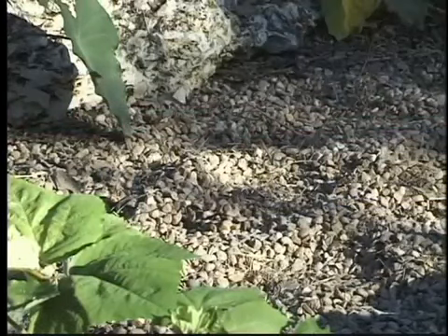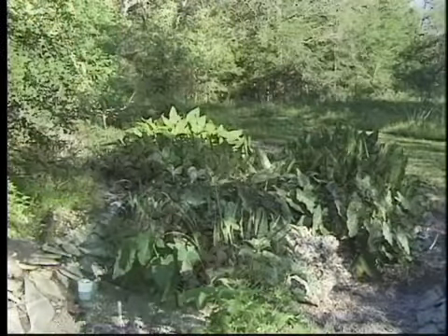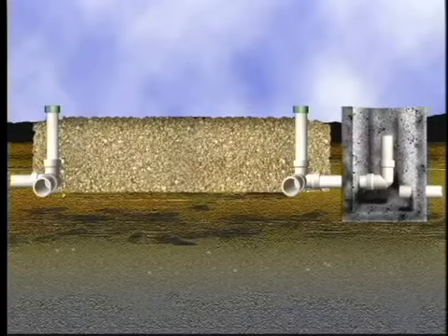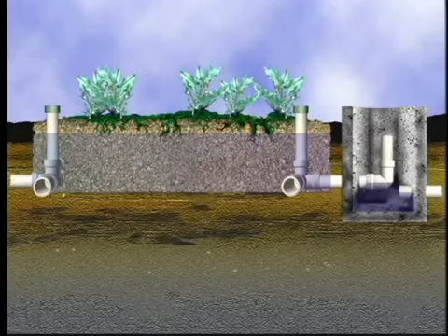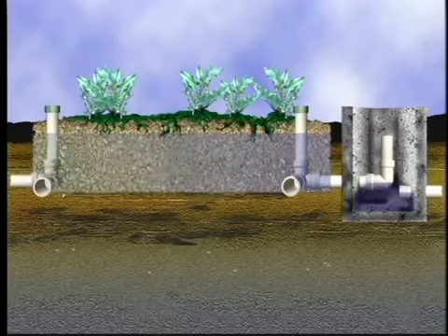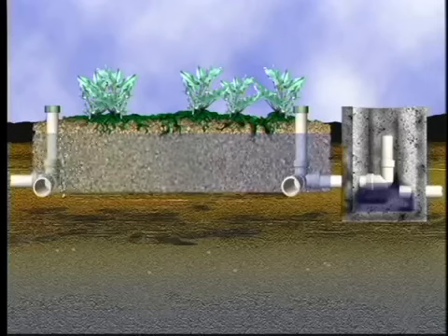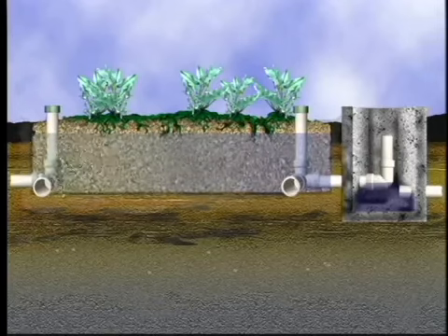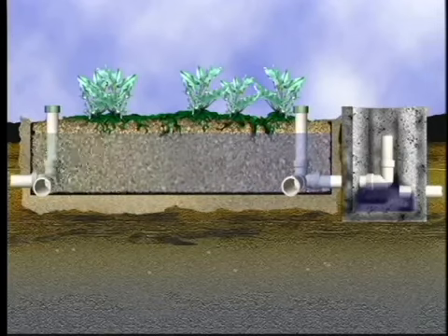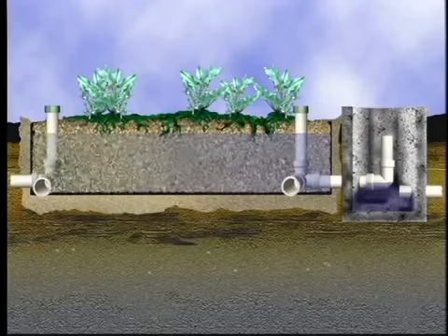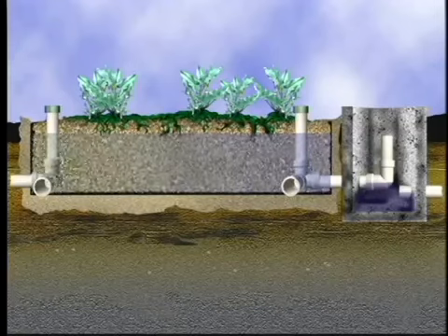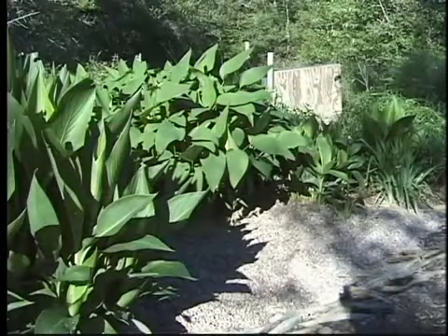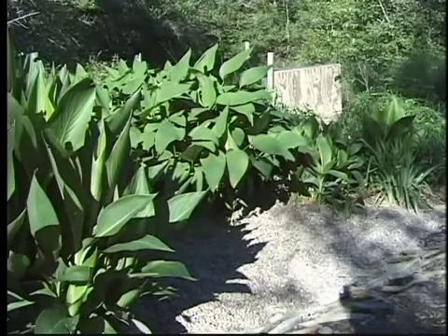These systems are designed to blend into and even enhance a landscape design. The wetland consists of a bed of graded stone, with water flowing just below the surface. Aquatic plants are grown in this bed, feeding on the nutrients, organic matter, suspended solids, and pathogens in the effluent. The bed is set in an earthen basin lined with compacted native clay, bentonite clay, concrete, PVC, or a similar water-tight substance. Plants in the wetland must be able to survive in a saturated medium.